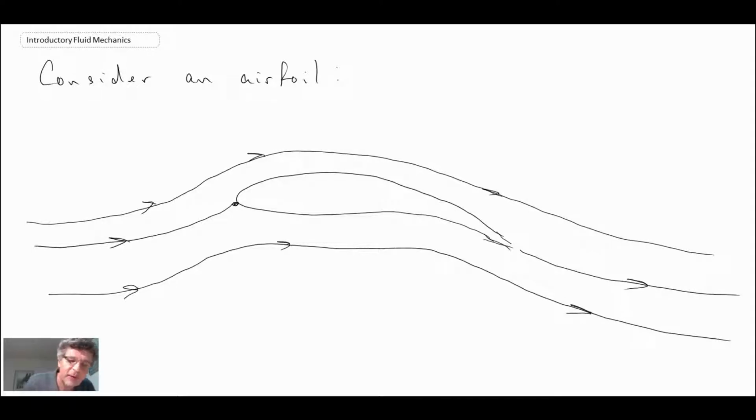And we have a couple of other points here. We have the leading edge, that is given the acronym LE. The trailing edge is given the acronym TE. And then we also have the angle of attack of the airfoil. That relates to the difference between the free stream velocity, which would be V infinity, and a line going from the trailing edge to the leading edge with respect to that free stream. That is alpha, and sometimes it's AOA for angle of attack. This is obviously an airfoil with a lot of camber.